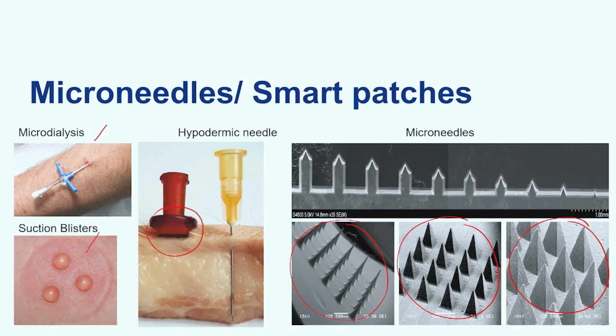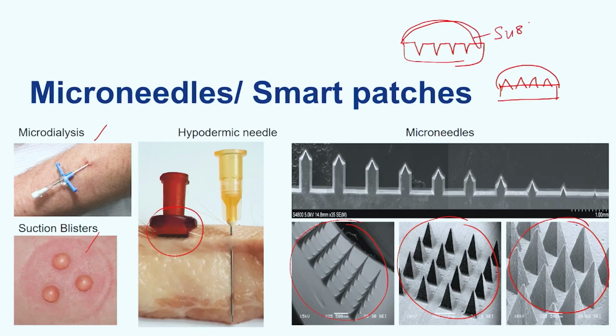So you take a block, so you imagine you have your solid block where you have your microneedles, and then you pour SU8 on top of this, and then you let it set, and when you peel it off you get your SU8, which will have the inverse structures, and onto this you can pour your SU8, which is basically a polymer again, a monomer mix, which can be polymerized by just shining light onto it. And then when you cut this off, you get your epoxy SU8 microneedles, which have the microneedle structures that you've been looking for. Simple case of molding and casting, right?